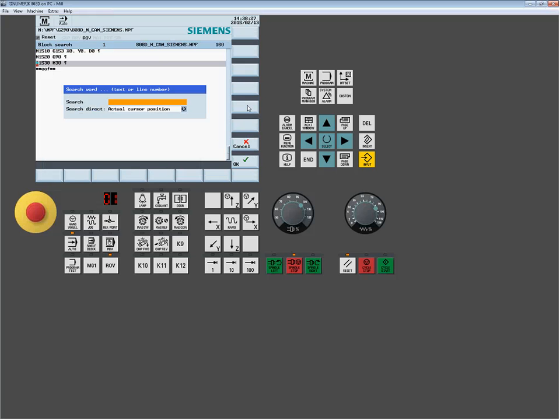Further down, I changed tools again. In this case, I'm using the same tool. I repeated the tool change statement. It's redundant, but when I'm bouncing around, it allows me to bounce a little further down the program. So I can jump over this tool, but still force a tool change down here if I wanted to maybe just jump over to the semi-finishing operation.